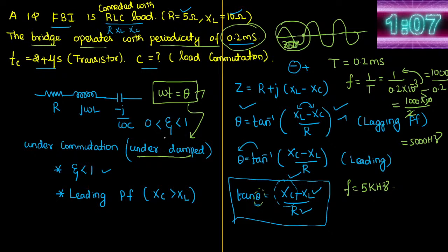Okay, sir. Fine. So from this, how can I express this? Here this theta is nothing but the circuit turn off time. Are you getting me? I'm telling you this minimum time should be equal to theta, and theta is dealing with the circuit turn off time. This is the only condition in load commutation, just remember this. And whenever they talk about a capacitor, they will give this condition, you can just equate it. Fine, sir. Let us continue further.